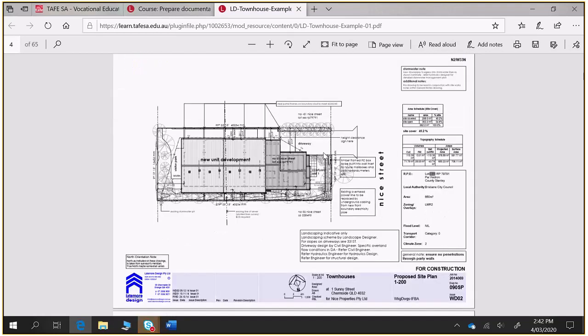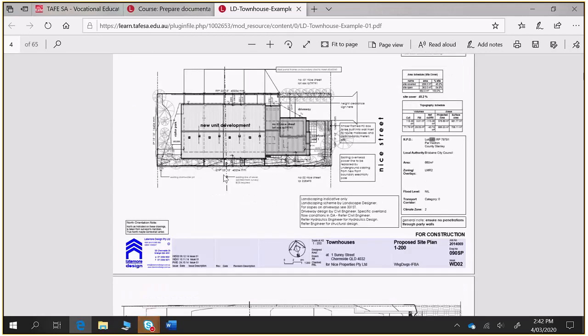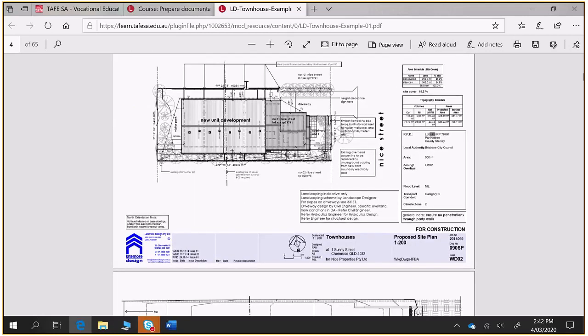And then right under that, the site plan. I don't encourage always putting roofing information on a site plan. I leave it off. Typically what I do is I show the outline of the building and then a dashed outline of the roof on my site plan, and that's it. I might show some indicative wall thickness, or I might have some wall and I'll hatch that wall, but keep it really simple.